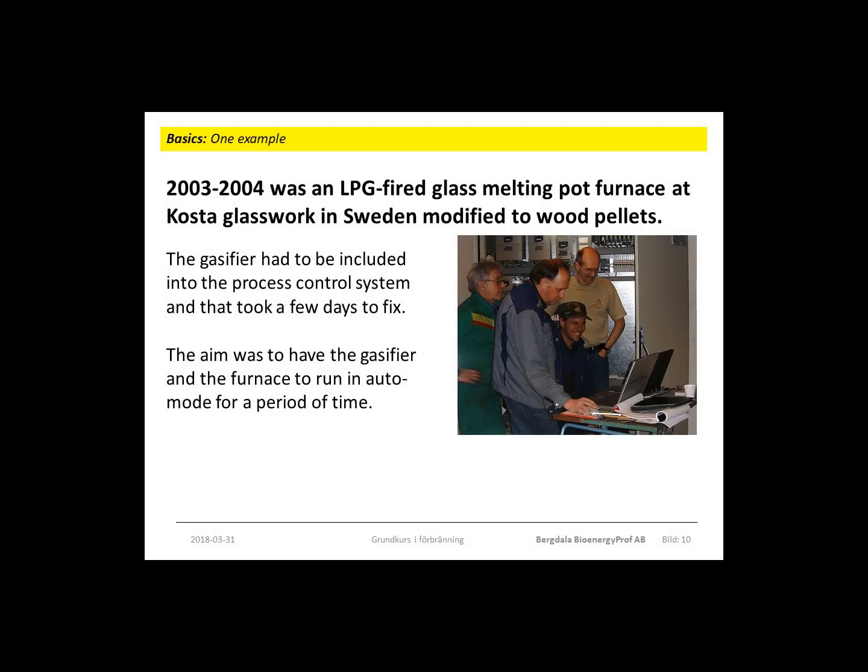Since the whole installation was only aimed for a short time, no real effort was made to save the thermal energy of the gasifier gas. Thus, there was a significant thermal loss and temperature drop in the connection tubes from the gasifier to the furnace, and when the setup was dismantled, we saw that tar had condensed inside the tubes.